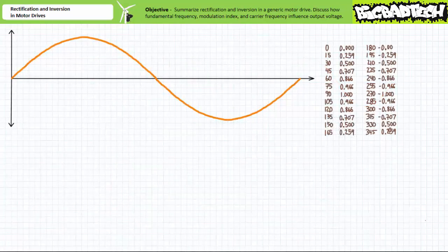First, you have to think of PWM in terms of average values for particular sections of a complete AC cycle. For example, if we chopped up an AC waveform with a period of 16.7 milliseconds, a period corresponding to a frequency of 60 Hz, into 24 different sections, each encompassing 15 degrees of a 360-degree cycle, each section could be considered as having a median value representative of that section. For example, the section centered at 0 degrees would have a median value of 0.